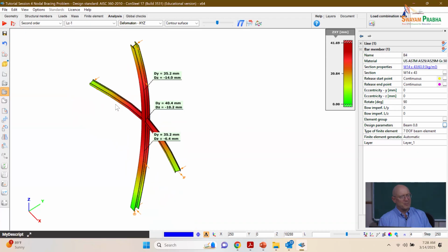In general, we would need to check that the W14 by 145 column, if it's bent into a mode that is an S shape, if it has an imperfection that's an S shape with an inflection point at the brace, that's the way that would be most damning in terms of imperfections on the column.